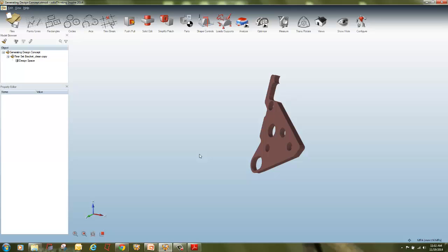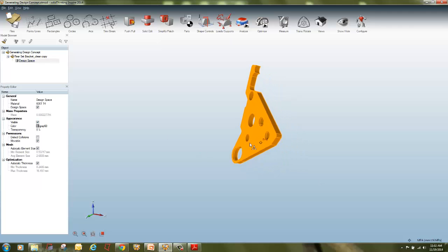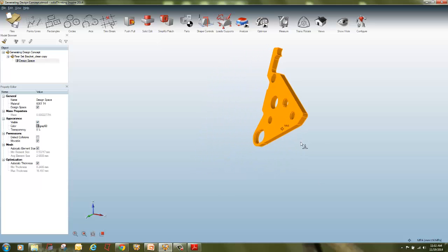Then to rotate the view using the mouse, hold down the right mouse button and drag the mouse. The view rotates using turntable rotation, which is similar to the movement of a record on a turntable. So hold down the right click and you can move the mouse like a turntable.